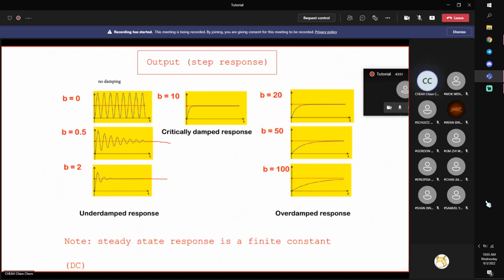We have seen this last time. I showed you these animations of mass spring damper systems. Imagine that you have this mass hanging on the spring. If you pull it away from the equivalent position, this is your initial position, it means that you make the spring store spring energy. So it has stored energy. Once you release the spring, because it has stored energy, you will move, but how it moves is very complex. There are 3 types of response we have learned: underdamped, critically damped, and overdamped.